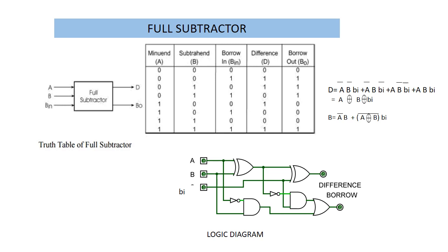So a full subtractor subtracts one bit B from another bit A when already there is a borrow Bi from this column for the subtraction in the preceding column, and outputs the difference bit D and borrow bit B required from the next column.